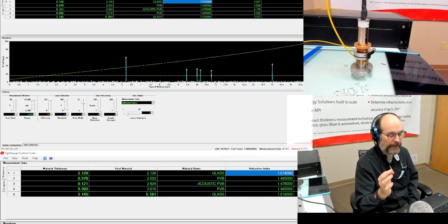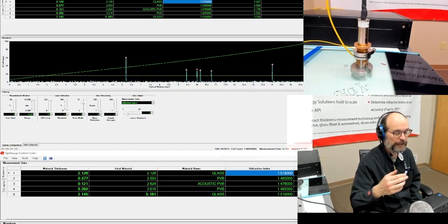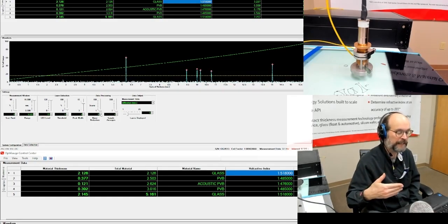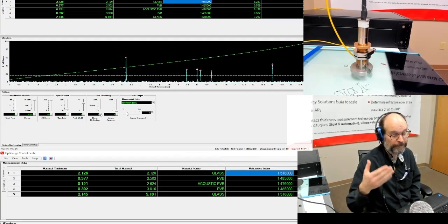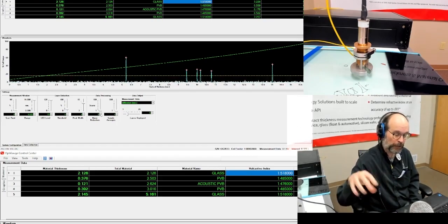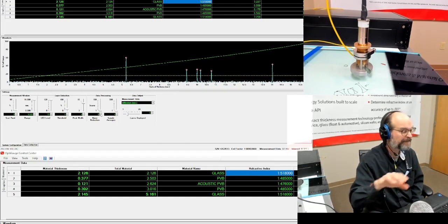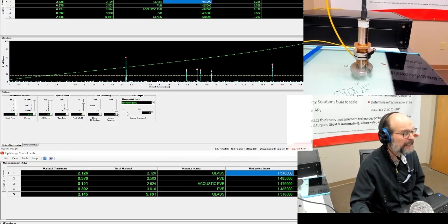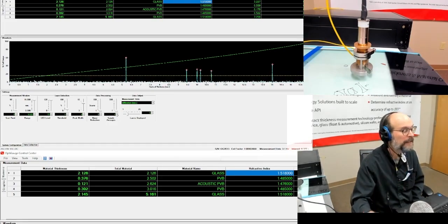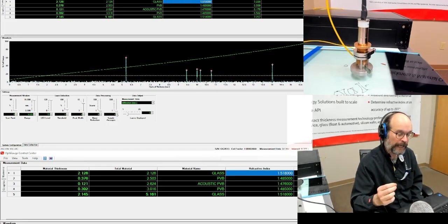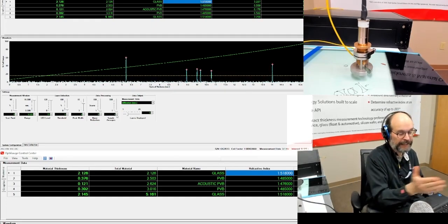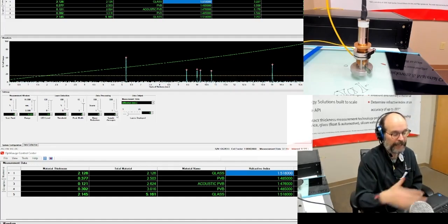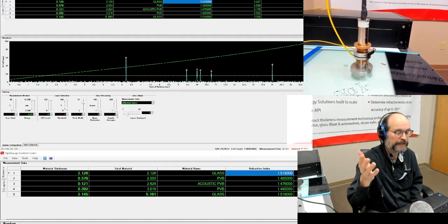What you give up with that is speed. So you're not getting a measurement every 50th of a second. Four basically measurement cycles are used to do some noise reduction. And averaging is similar. You're going to give up speed for accuracy. Sample average is just that: how many scans do I average before I present data results.